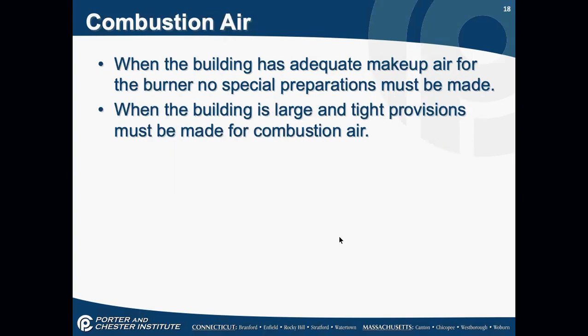When a building has adequate makeup air for the burner, I don't have to do anything. The building will allow air to circulate on its own. When a building is large and tight, we have to bring in outside combustion air. If it's tight construction, I have to bring in outside air.